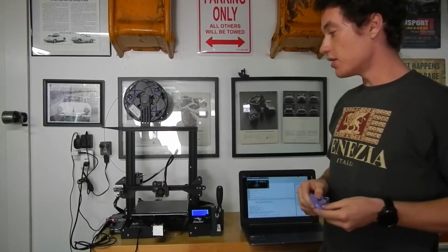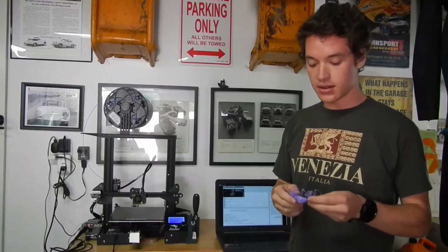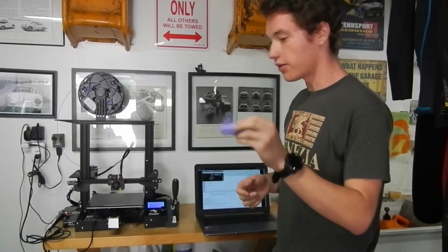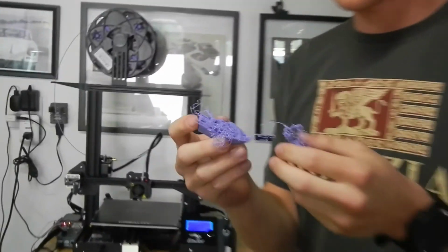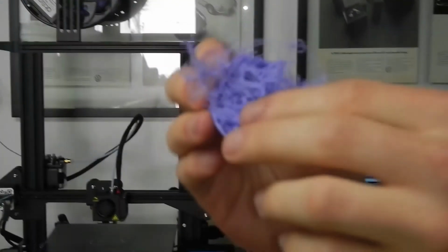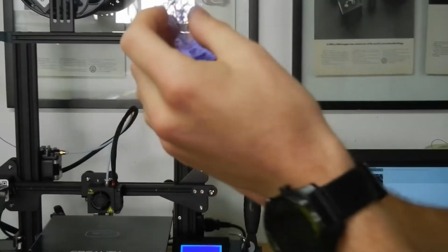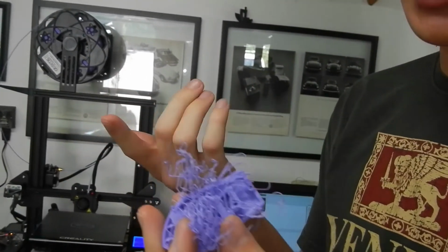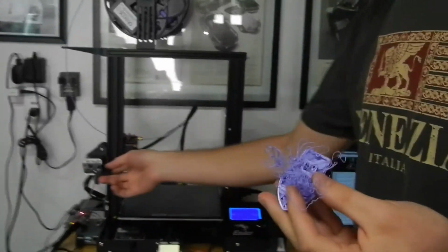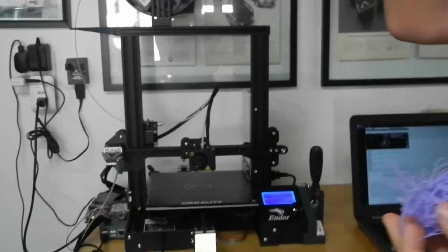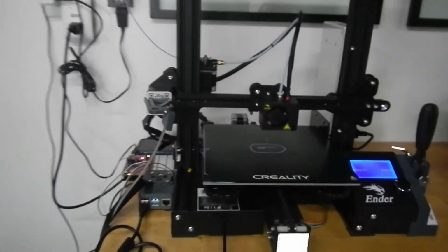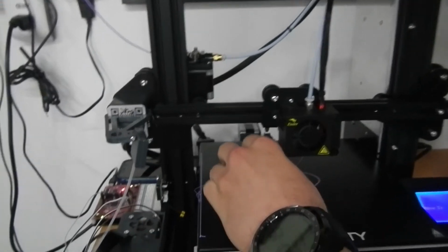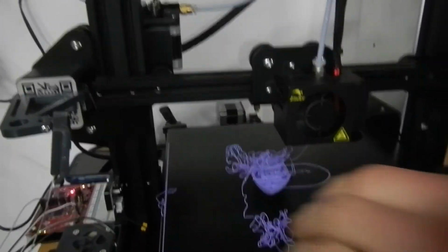Okay, so the last feature that I'm going to showcase is error detection, or print detection for a bad print. So you can see here that this print has failed, and when prints fail, the printer starts printing on nothing and it creates these long strings, which obviously have many edges. So I created an edge detection script in Python that runs off this camera. So when I place this failed print in here, it should detect the failed print.